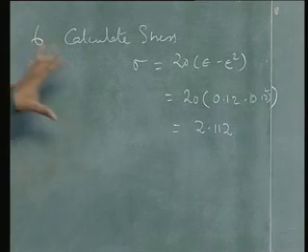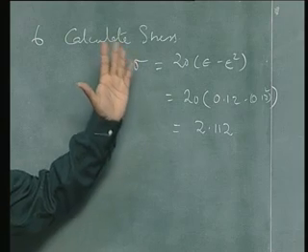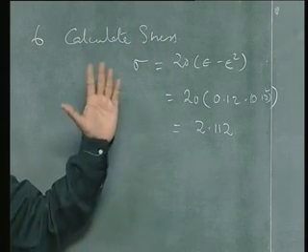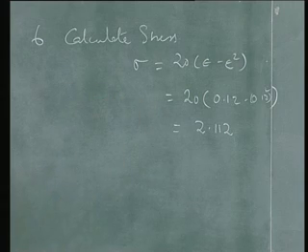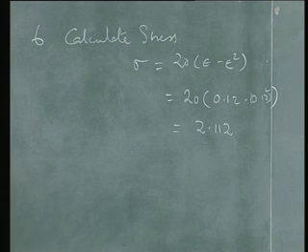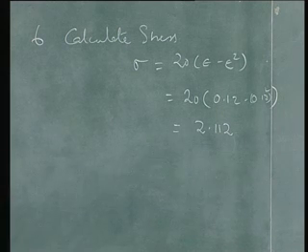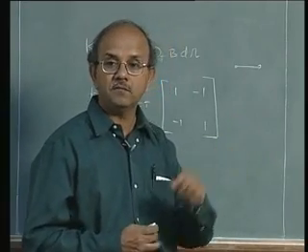See, this calculation of stress part is usually called the stress update. This may be a very elaborate procedure when we come to elasto-plastic analysis, because you may not have a beautiful relationship like this, and I have to satisfy what I called just now as a consistency condition. That is, the point should lie on the curve.